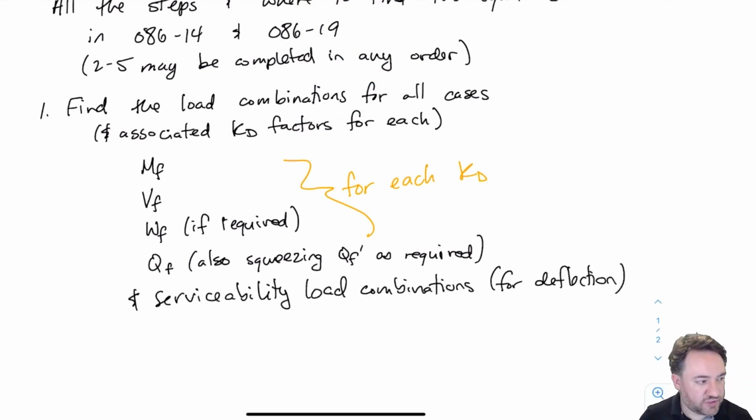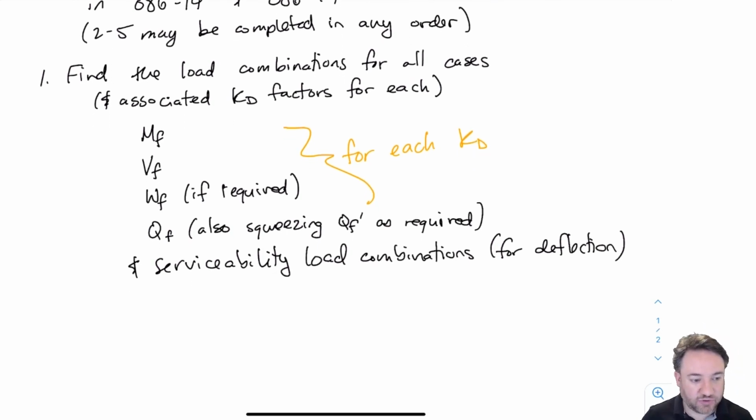So then once I have all of those load combination factored load results for ultimate limit states and serviceability limit states, then I can go ahead and start checking my resistances against those loads. So the first one that I'll talk about, and again, doesn't matter really which order you do these, sometimes maybe it's going to be clear that one of these is going to tend to govern in your problem. And so if you're doing a design and you're trying to pick different beams, and you know, for example, that this beam is particularly sensitive to shear, like it's going to be close to the shear resistance, then maybe I'm going to design check beams and then check them against the shear until I get one of those that governs. And then after that, go ahead and check all the others, the ones that aren't going to be so critical.